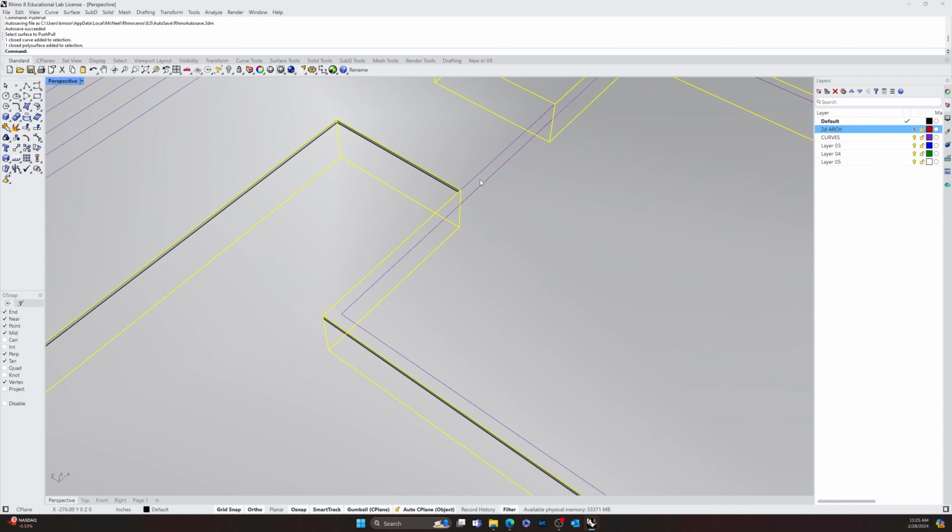All right. And you can see also these are kind of edge to edge, which I might not like as much. So let me go ahead and undo that. Now I'm going to actually just pull down this bottom here. Let me do it like maybe 3 inches. And then I'm going to array curve. So with the object selected, then it's asking me for the path. Click on the path, curve. And then the number of them, I'm going to do 20.